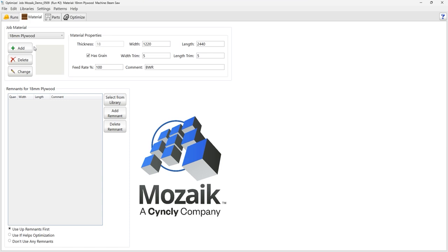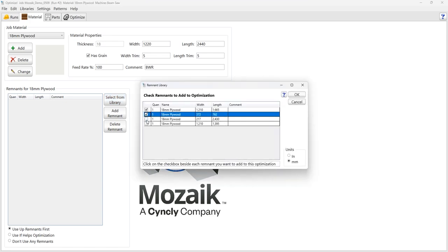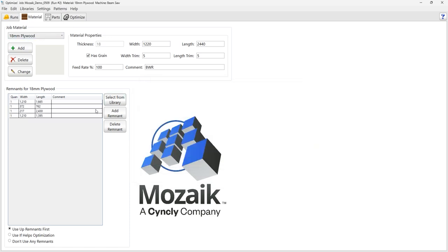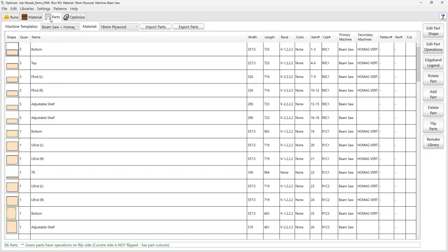It's a very important function here, and the customer may ask this question several times, that what happens in case if we have some material already in the stock or as off-cut size. So Mozaik is also going to maintain that information if there is an off-cut. So if you have off-cut, like for 18 mil, I have selected the off-cut. So it means it's going to cut the off-cut before it uses new sheets.